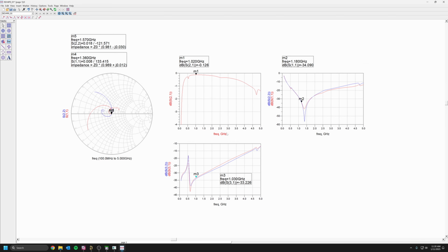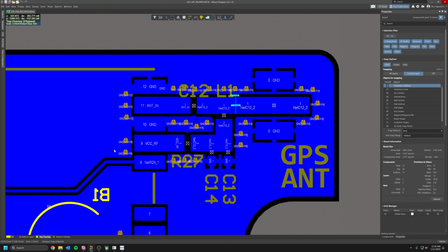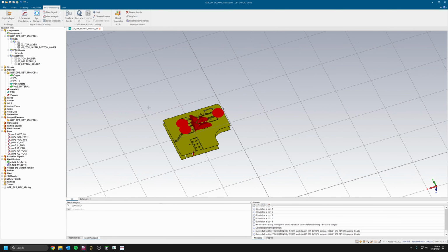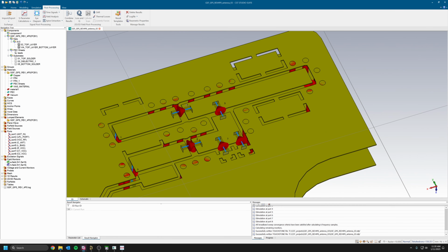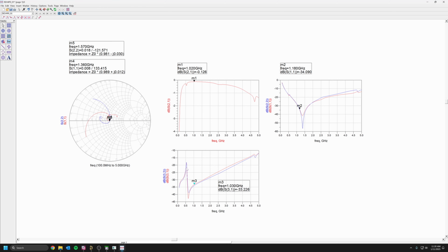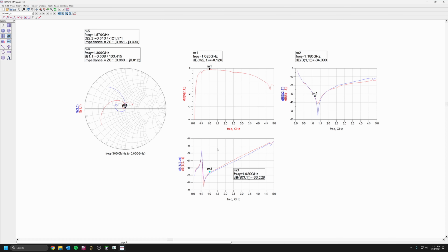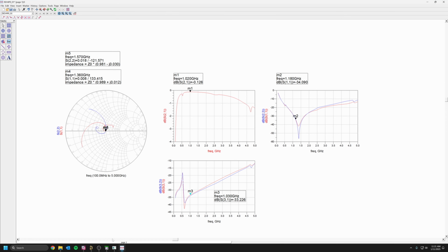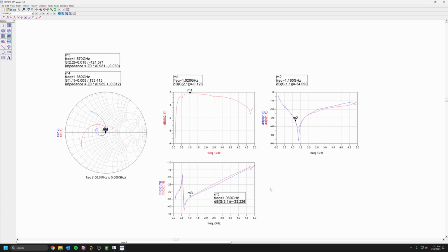So in the end, this is what I wanted to show you today: how to take an Altium Designer project into CST, reduce the board size so we can optimize the simulation to the specific area we're interested in, place the different ports, and then run the simulation. Then I showed you how to import the data into ADS so we can analyze it and conclude if we need to rework the design, or if it's good enough, we can fine-tune the RLC components to optimize the performance.